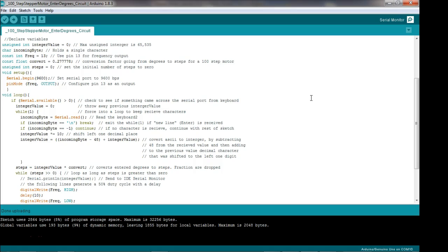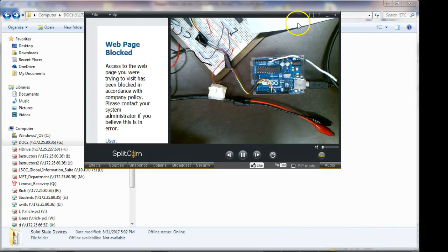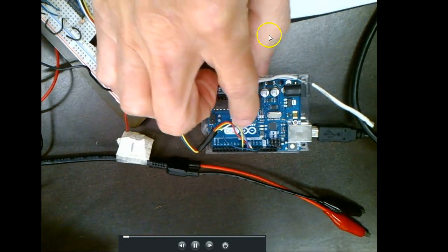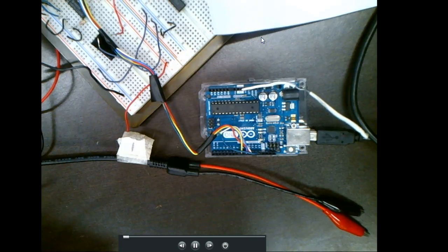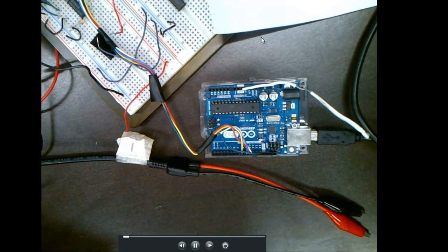So I could go out and pay a couple thousand dollars for a PLC to run something that I don't need a PLC for. This guy's got outputs on it, just like a PLC. Let me bring my camera up. So all these are ports over here. They're programmable. So what that means is you can make any one of them an output port, or you can make any one of them an input port.